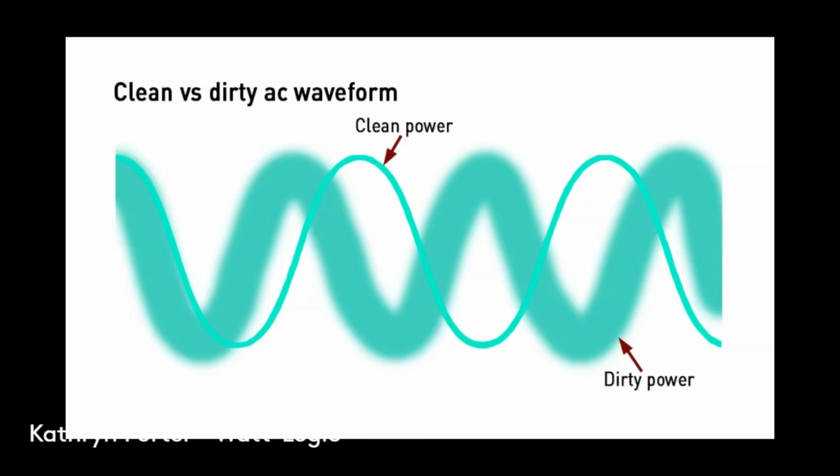Keeping in mind this is basically something that you get for free with conventional generators. So now suddenly it's something you'd have to pay for with wind and solar, and if they're having to reduce the amount of electricity that they can sell day in and day out, then that could be quite a significant cost. Thirdly, inverters don't respond automatically to changes in voltage unless they're programmed to do so. Some are set up to help with voltage and reactive power, but many of the older or cheaper models just disconnect when the grid signals start to deviate from their normal parameters.